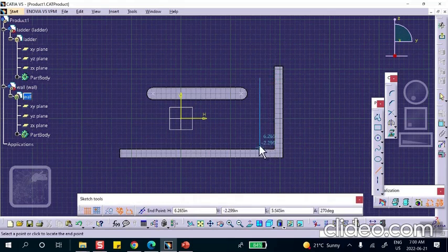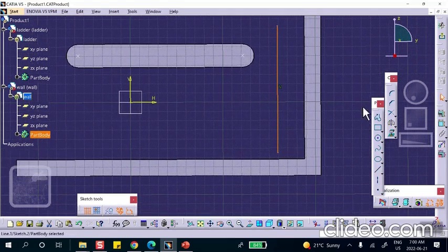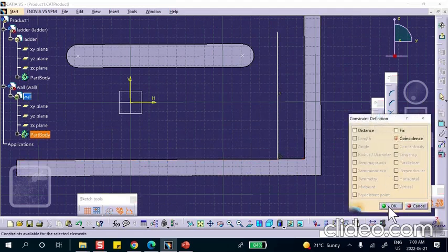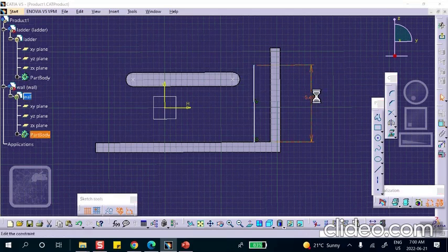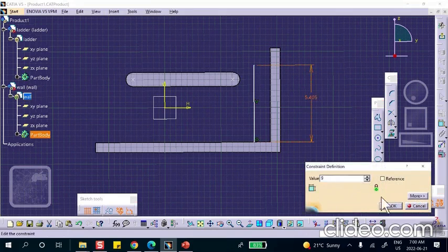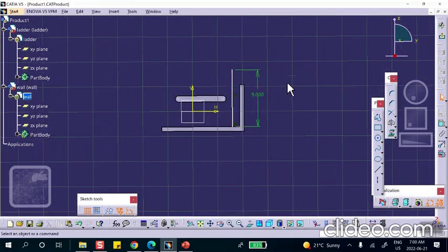I'm going to make sure that it actually touches at the bottom point. So this point, although it's not important, but I will do it anyway. This point, control that point, that line. We're going to make it coincident so that it lifts it down and puts on it. Okay. And let's see now, this thing, let's make it about 8 inches. Okay, 8 inches high, maybe 9 inches high. There, I'll make it 9 inches high. All right, fine, 9 inches high. Very good. That's pretty much it.